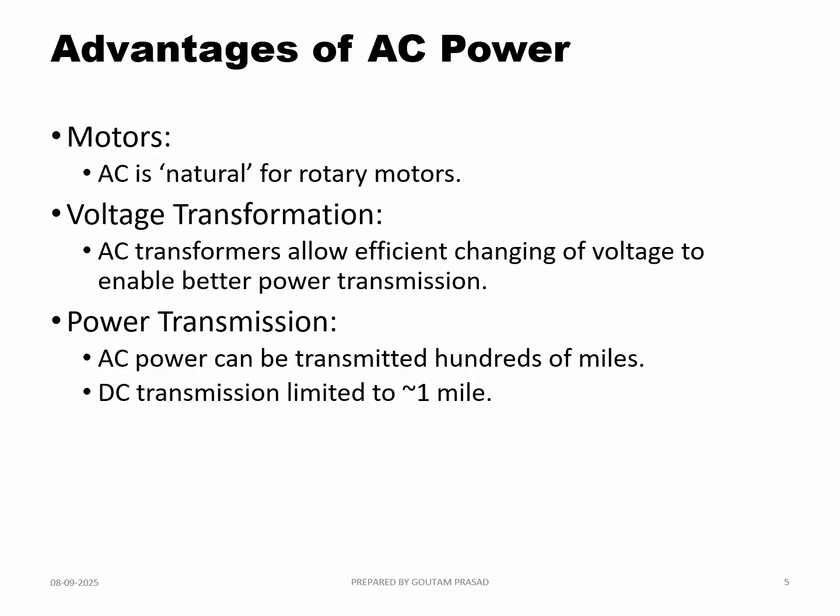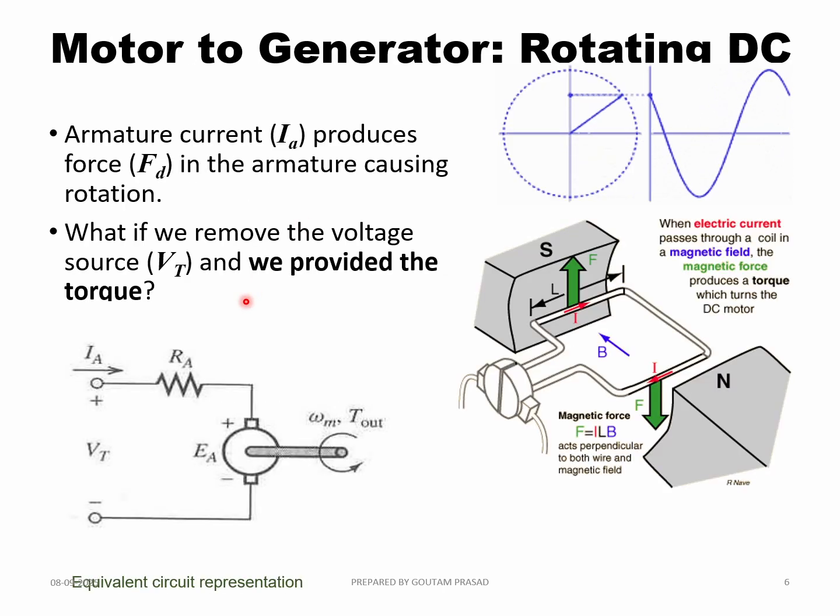That is the advantage. So let's try to understand the functioning of the motor, DC motor basically, in order to understand the functioning of the single phase AC generator. So here on the right side, you can see the setup of a DC motor, having two segments and a single loop coil. Basically, it is fed with DC power, and this conductor carries the current I flowing through it.